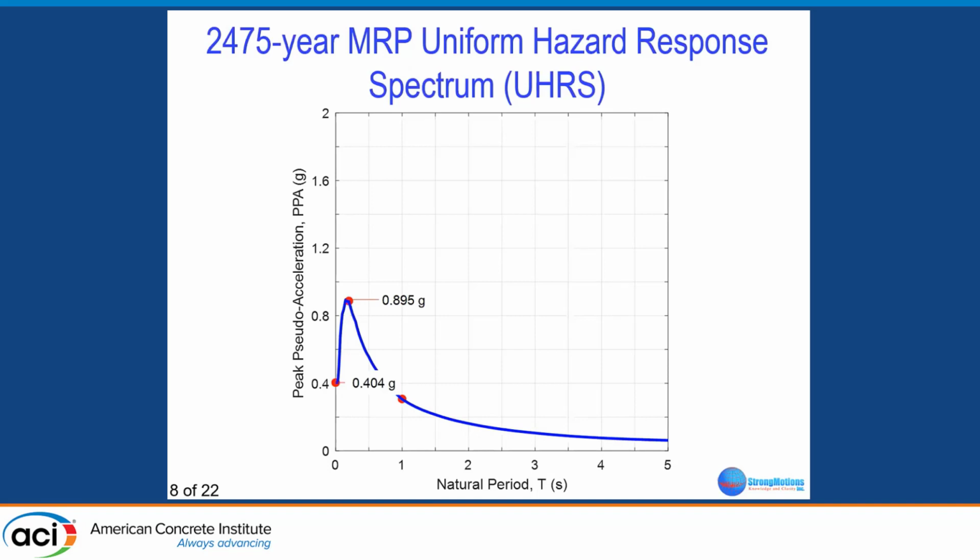And then we use ground motion prediction models to generate a smooth spectrum passing through these 3 values provided by the USGS. So these are the 2500 year mean return period uniform hazard response spectrum. Meaning that all 3 values, and all the values on this response spectrum, have the same probability of exceedance. That is why it is called a uniform hazard response spectrum. And remember that this is only for rock. We have not done the work of the geotechnical engineer yet.